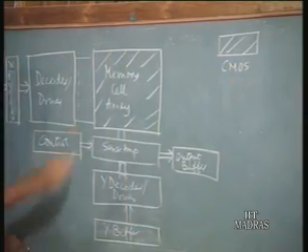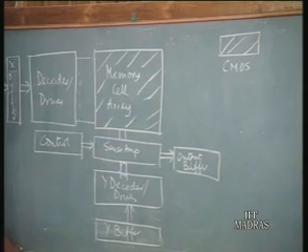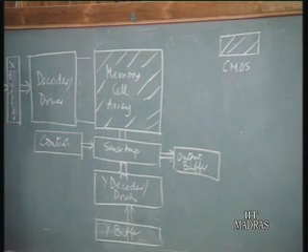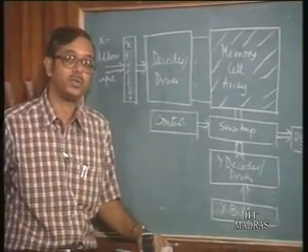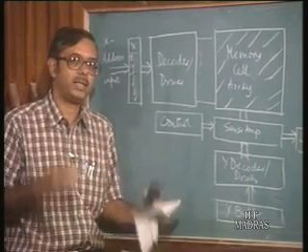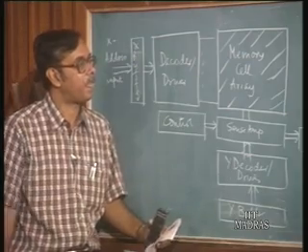Okay. So, the memory cell array even in a BiCMOS is going to be a CMOS. So, we do not introduce bipolar transistors in the memory cell array, because the bipolar cell takes up a lot of area, and also the power dissipation is going to go up. Okay. So, what we are designing is for a large memory.